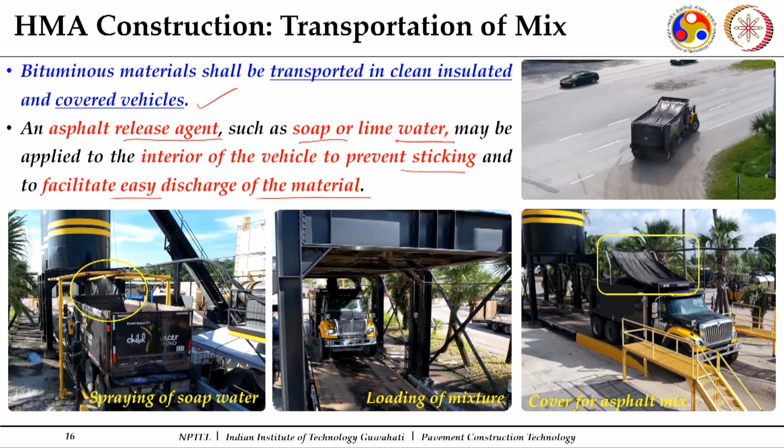But the controlled use of release agent has to be ensured. An uncontrolled higher quantity may hamper your mix, because binder is there, so release agents may lead to concerns with your bituminous mix. Once the release agent is added, the tipper takes your mix, and it is to be covered. It is important because if some rainfall event takes place, and the transportation requires a good amount of time, the temperature should not fall down. That's why they are covered and then transported to the field.